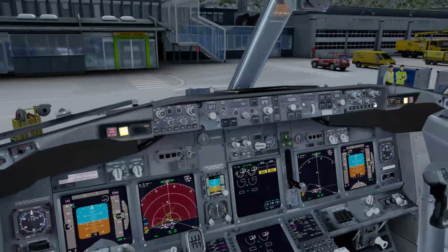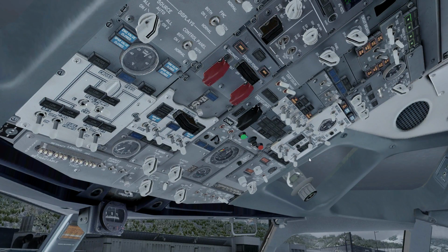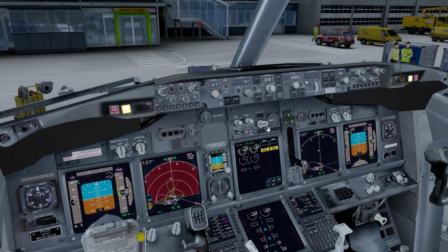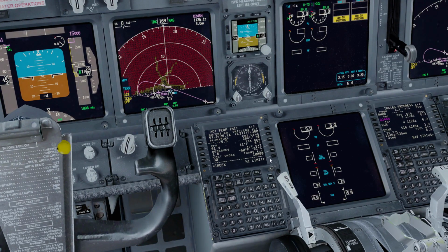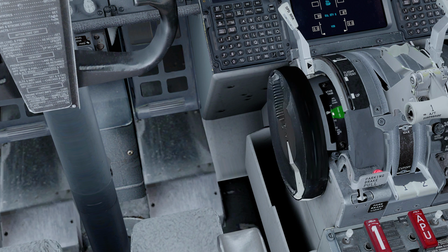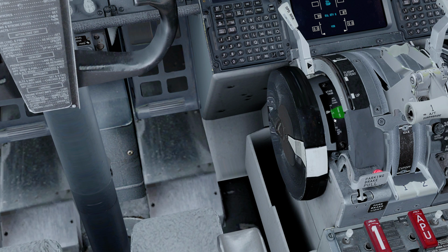For now we're going to do the before start items and then the before start checklist. Just make sure that the hydraulics are on, make sure that the doors are now all closed. You can turn the packs off, alright, because we need all the bleed air from the APU in order to start the engine. So temporarily the cabin will not have air conditioning, okay? So keep that in mind. Again, the anti-collision lights are on. One thing you also want to make sure is that you set the trim right now. So we can just go to the takeoff page. The trim should be 3.88. So this is 4, this is 3, so it's already nearly there. Let's put it on 3.88. There we go. That's about fine for now.